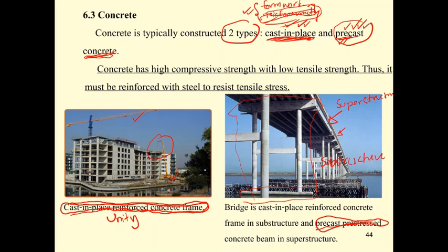a big structure, such as this bridge, needs to have a good plan. Okay, if these things go together, it will finish very early. While you construct the substructure, which includes the pier, the foundation, the pier, and the cross beam, you can cast the pre-stressed concrete, and then you ship it and you install it.